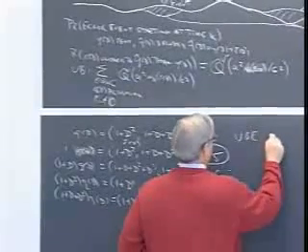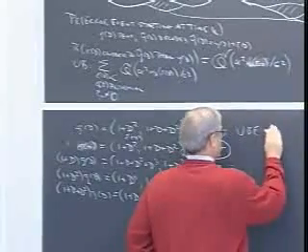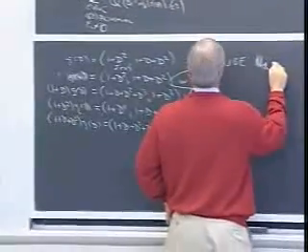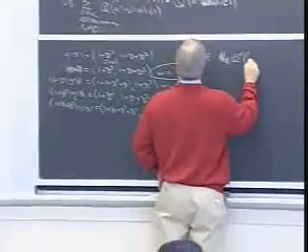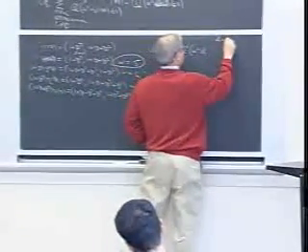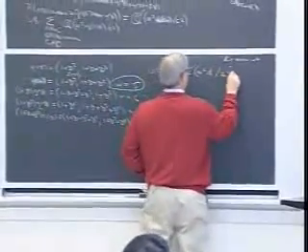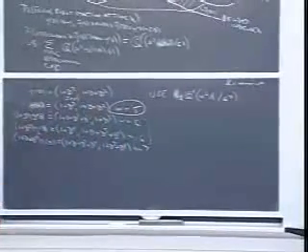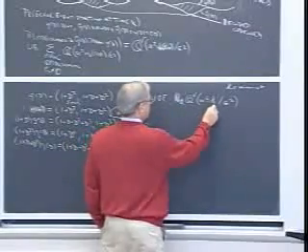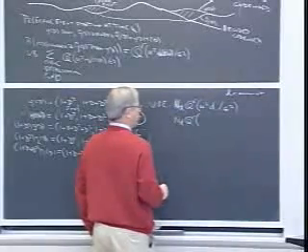which is simply, let's just take k, n d, the number of error events of minimum weight d, times Q to the square root of alpha squared d, where d equals min weight, over sigma squared. Okay, in this case, nd equals 1, d equals 5. Let me take this one step further. nd times Q to the square root of,